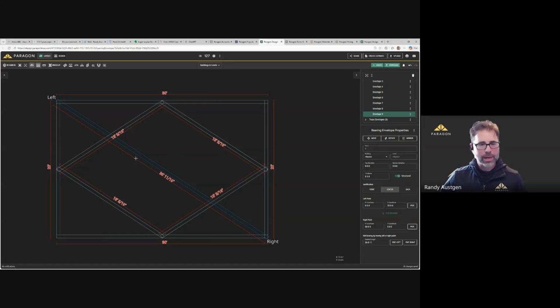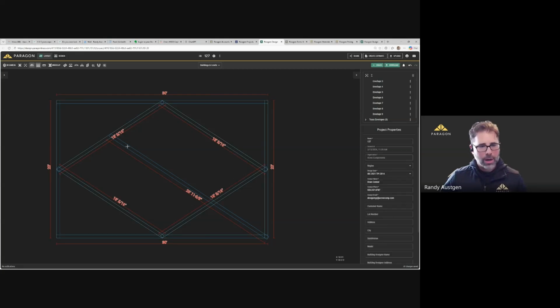So with that in mind, if I select this member and I want to trim this back, trim extend, say to this line, what's going to happen? Any ideas? Is it going to keep the long end or the short end? Let's give it a go. So it's going to keep that long end. Thank you, Lane. There we go.